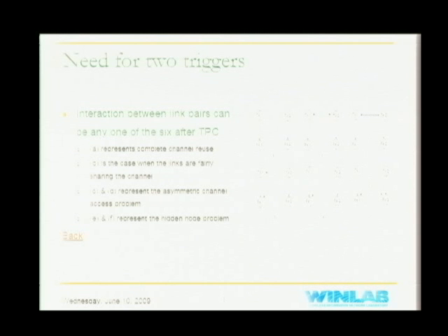Scenario C represents an asymmetric channel access condition or a pure exposed node condition, where transmitter 1 is able to carrier sense transmitter 2 but transmitter 2 cannot, and it always perceives a clear channel. So it hogs the channel and the TX1 RX1 link is stopped.